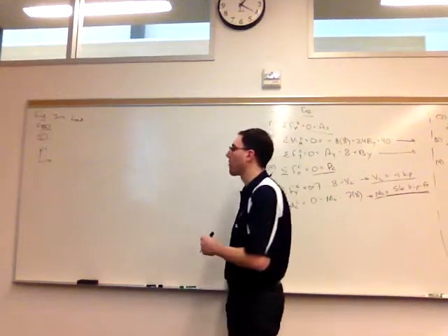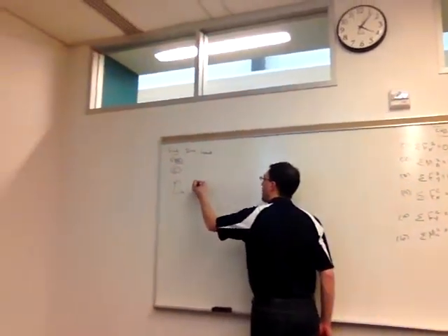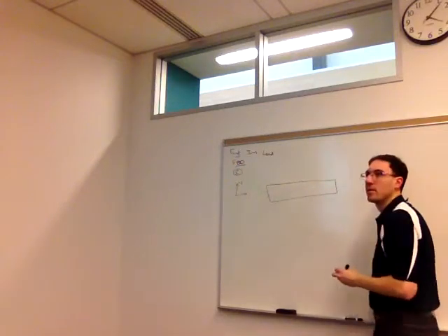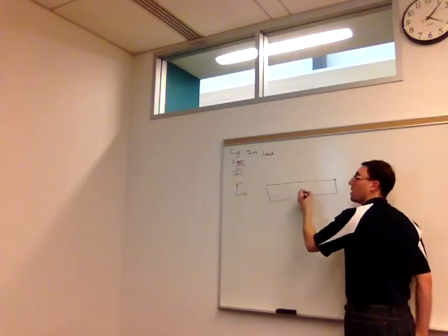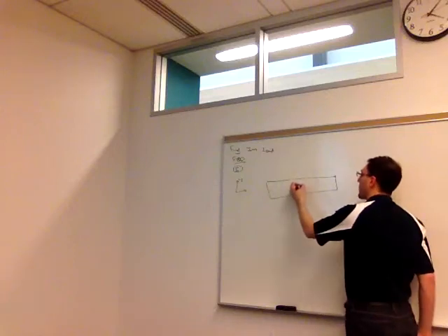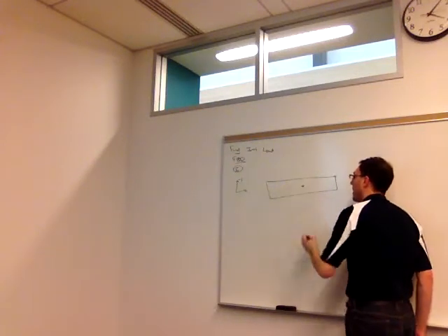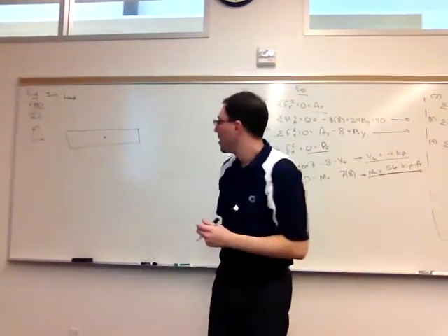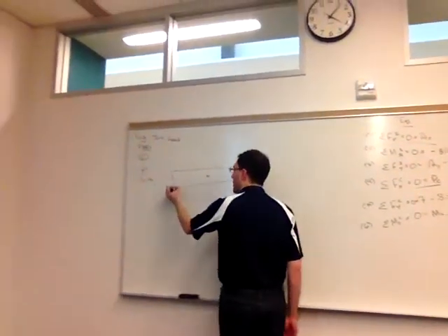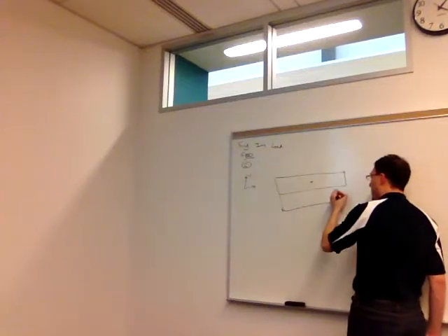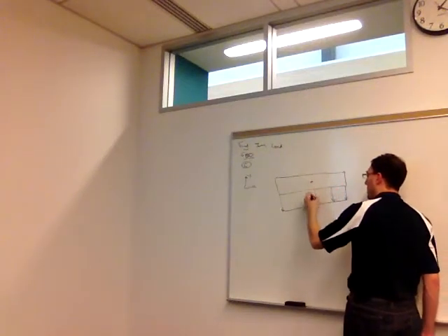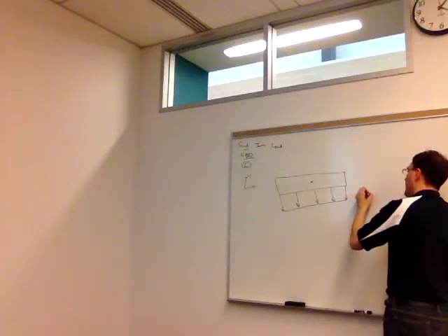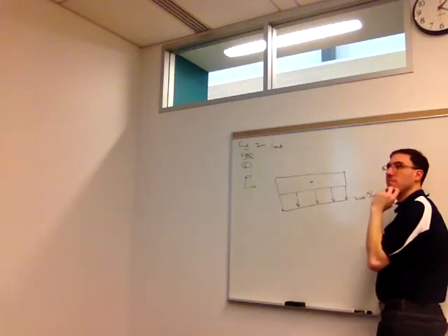We'll begin with the external free body diagram of this beam. We're not told the thickness. It's going to turn out not to matter for this example. We have a distributed load acting on the bottom of the beam, with an intensity of 300 newtons per meter.